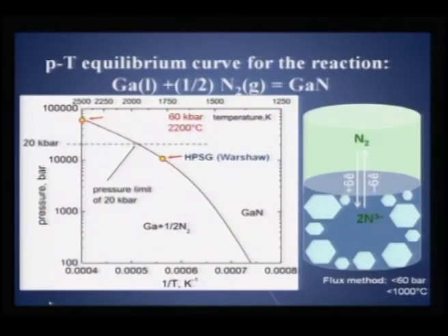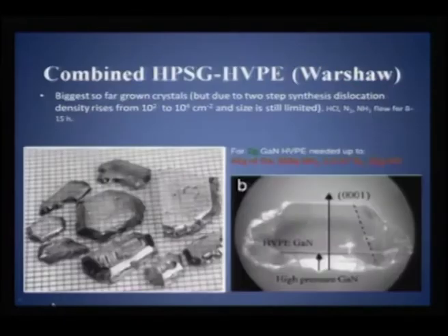So this is a typical profile of your pressure temperature graph, which is required for achieving gallium nitride formation using flux growth, and typically the size of the crystals can be as large as this. So this is achievable if you can get gallium nitride of say 2 gram quantity if you are going to start with 40 grams of gallium and 600 grams of ammonia and hydrogen.